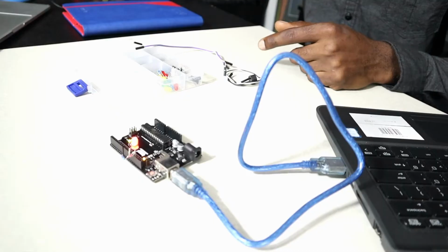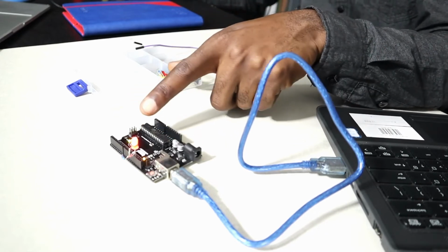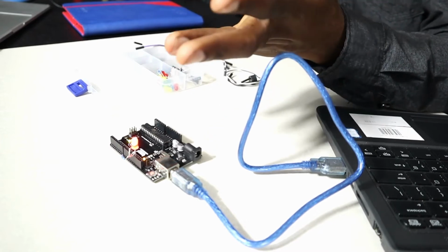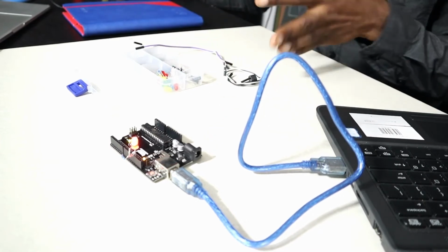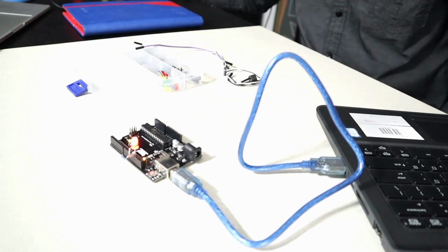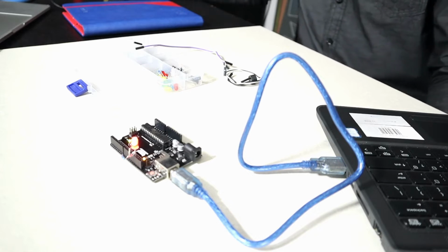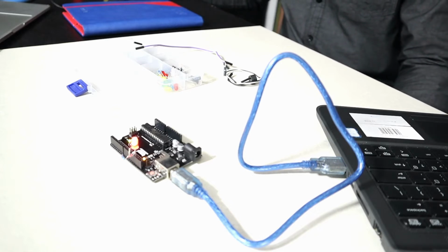And also you have to be very careful because you are tapping from the controller directly. What is actually powering this is the controller. So you don't have a shield, something that acts like a buffer, protection to protect the microcontroller IC. So you have to be very careful whenever you are tapping from the chip directly to power your LED. So that is how it works.